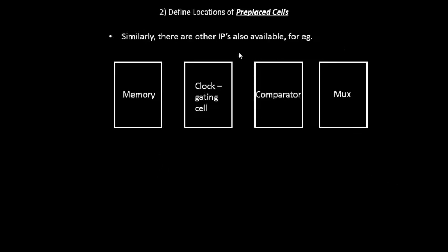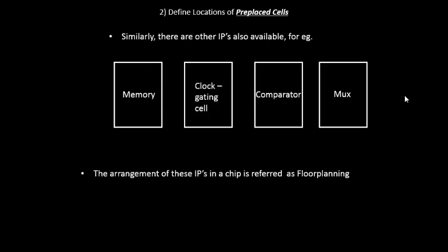So this need not be implemented multiple times, because this is a part of your top level netlist. They perform some functions, they receive some input pins, some input signals, they deliver some output signals, but the functionality of this particular cell will be implemented only once. And that's what we call pre-placed cells, because these cells are just placed once in the chip.